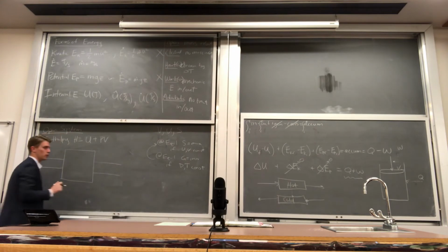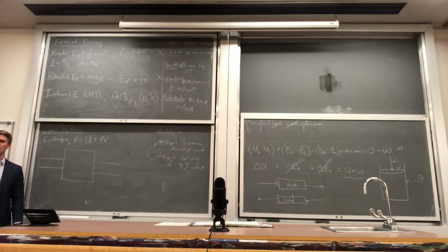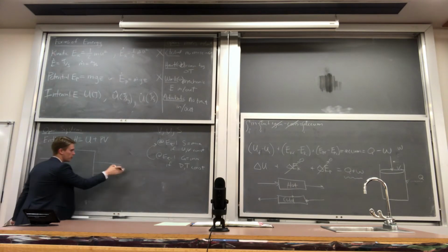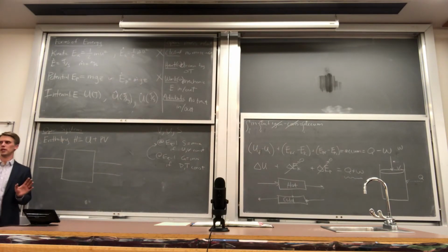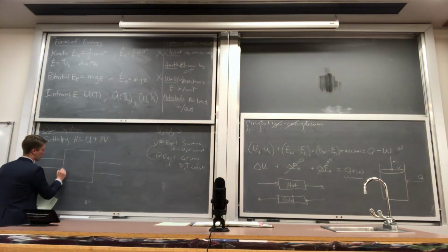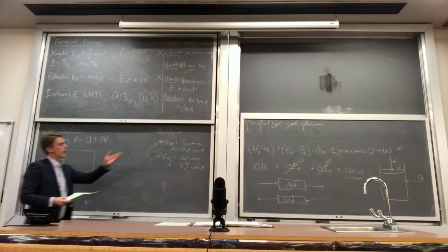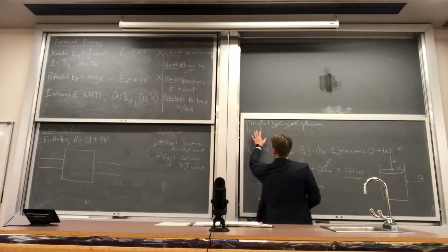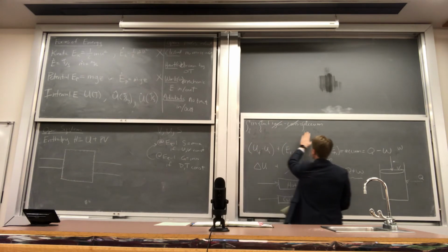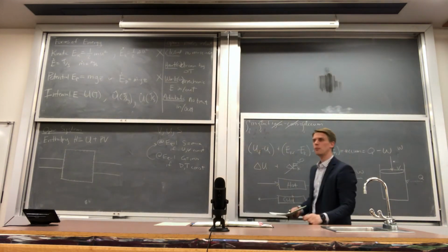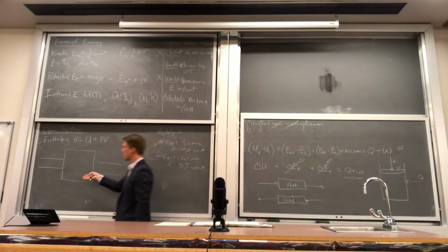Now enthalpy is a super useful thermodynamic state function, and it's because of open systems that we use it. So if I have a stream flowing into this process, which I drew as a pipe, and a stream flowing out, and we neglect the kinetic and potential energy, our system is this box here. When I perform an energy balance on this box, I have to consider the rate of energy flowing in, the rate of energy flowing out, and the imbalance is either going to be an accumulation or some heat or work loss term.